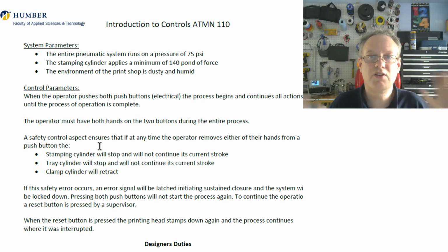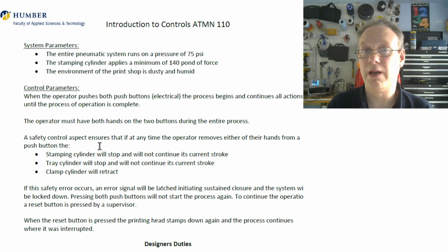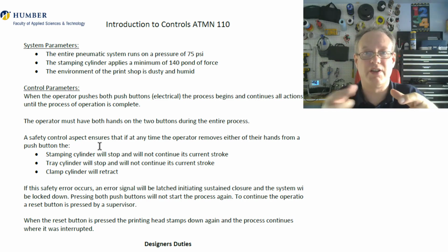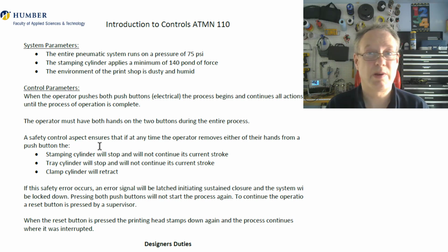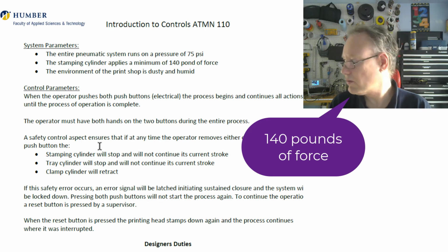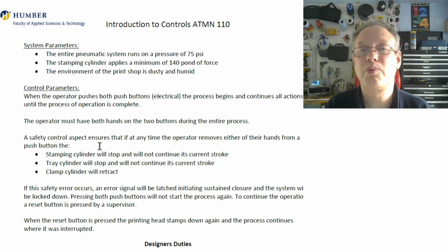So that's a lot of weight. Again, you don't have to calculate the 200. I'm just saying it's important to think about the fact that the stamp is really heavy because it could be a runaway load. Huh. Maybe there's something about a runaway load that you can manage somehow with safety? I wonder about that. Okay, let's continue. So the stamping cylinder itself has to apply that. So the actual size and dimension of the cylinder has to be established because you know the pressure. The pressure is 75 psi. So if you wanted to apply 140 pounds, maybe there's some calculations you can do. But you don't have to do that for your preliminary design.